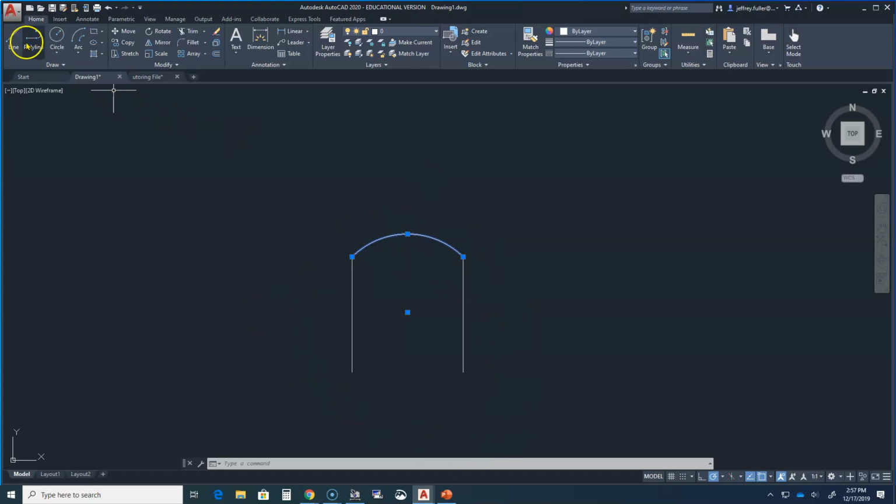If you start the line tool, then hover over the arc, the center reference point will light up. Draw 2 lines from the center point to each end. Then place an angular dimension between the 2 lines, and you'll get 90 degrees.